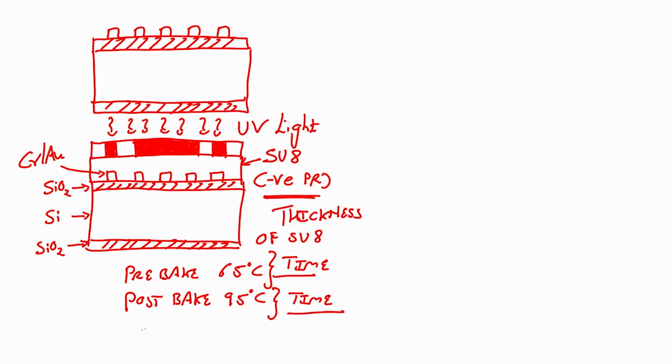This is not anymore 1 minute like we have seen in positive photoresist, alright. After post baking I will develop the wafer in the SU8 developer.